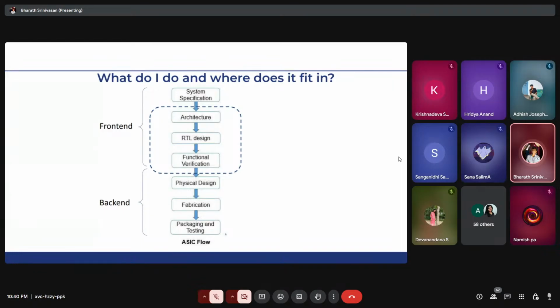But up until the PD and everything, and after that, post tapeout, there is a set of testing as well. Post synthesis validation and stuff. So you need to check that out as well. They might not ask you, but it's good to know the entire flow. But at least up until the PD, you need to know what each step is, what the sub processes of all these functional verification activities are, and you can get the details online.